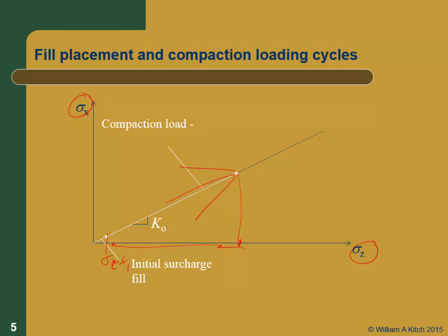So I've applied a stress, and I'm going to unload. Is my horizontal stress going to go back down to the same level that it was before I loaded, or is it going to be higher than what it was before I put the load on? Am I going to lock in horizontal stresses, or am I not locking horizontal stresses? Think. I feel like you're all dead.